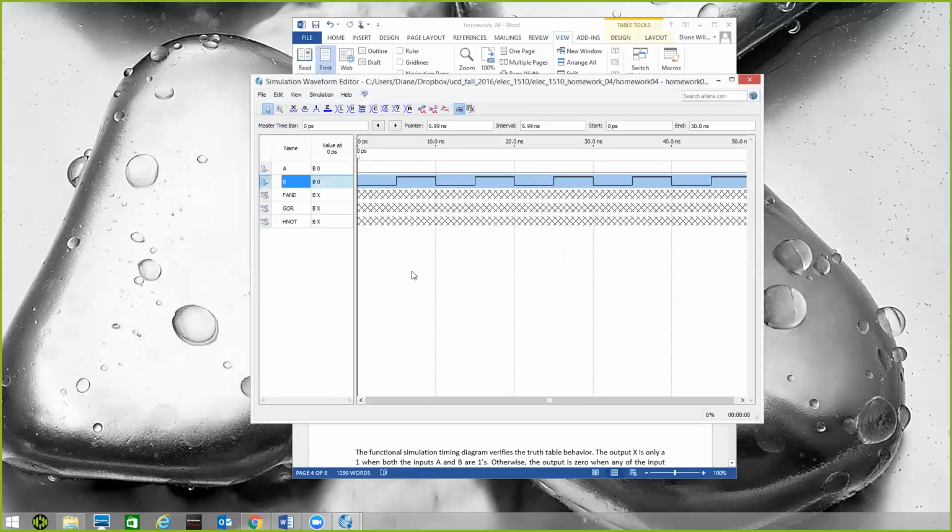50% duty cycle. And what that does is notice right here we're at 0 picoseconds. So between from here to here, 10 nanoseconds. 10 nanoseconds was our time period. In there we get one complete clock cycle, and we use the default 50% duty cycle, meaning for half of that period, or 5 nanoseconds, right, for half that period. So what I did was I right-clicked on this to move this over here. So from 0 to 5 nanoseconds, our signal was low. And I'll right-click on this again, the pointer. And then from 5 to 10, our signal was high. And notice this just oscillates between 0 and 1 all the way across here.